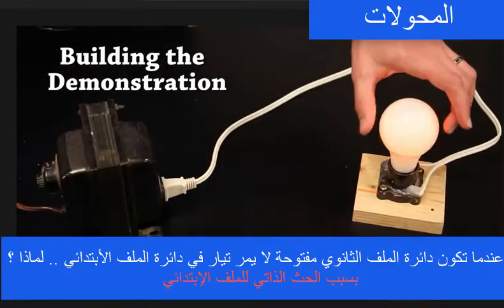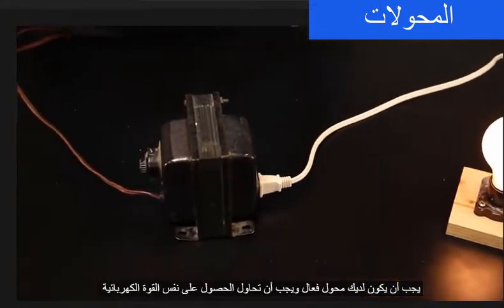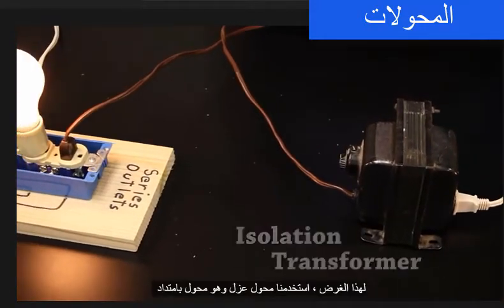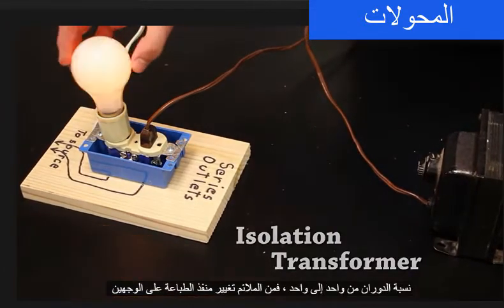If you want to do this demonstration yourself, you must have an efficient transformer, and you should try to have the same wattage bulbs at their appropriate voltages in the primary and secondary circuit. For this purpose, we used an isolation transformer, that is, a transformer with a turn ratio of 1:1.